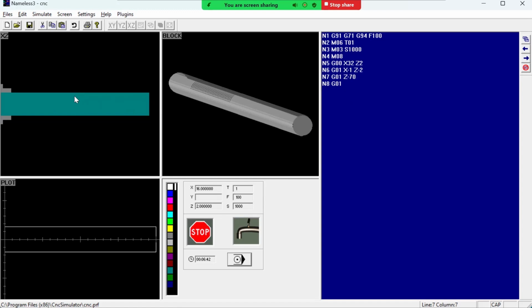And now you see this location of the tooltip will be treated as the origin. So we are only required to change the x coordinate to move it at the top. We won't be changing the z coordinate here. And treating this as the origin, we just need to type x1, because in the diameter coordinate system, this distance is 1 unit. So now the tool has been relocated here, and we are required to move it back to this point.